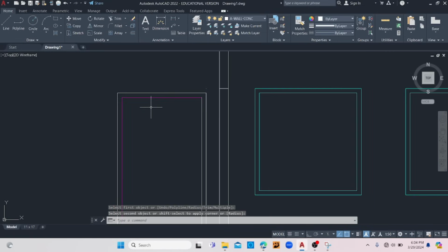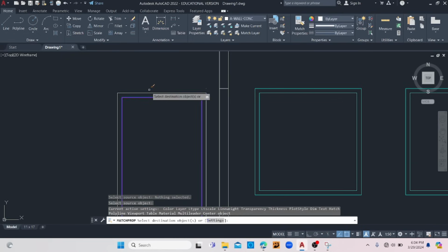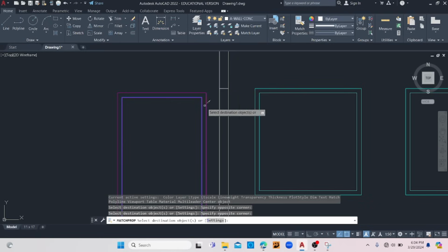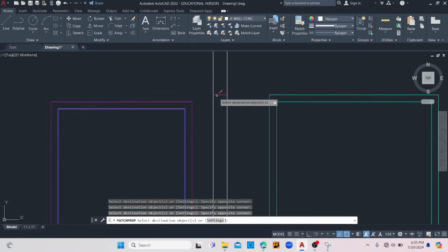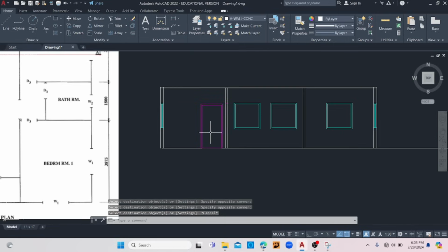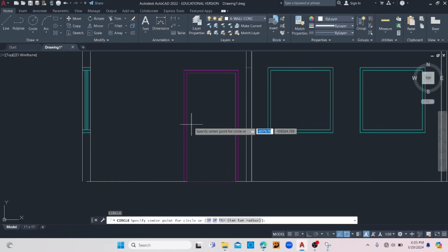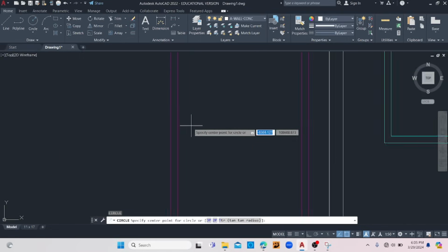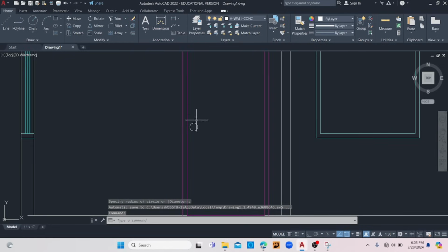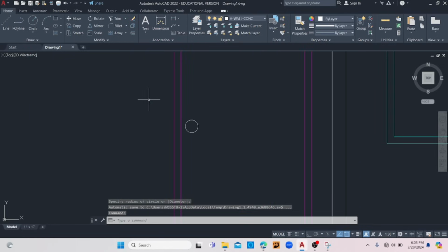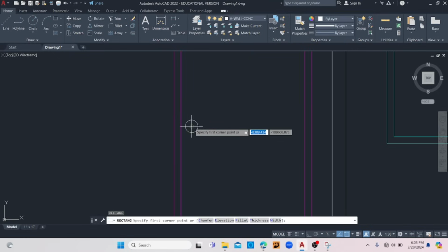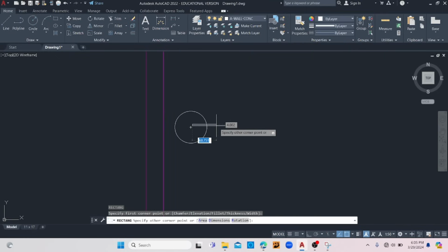Let's just place everything on the door layer. Let me do the same for the passage here earlier as well. Alright, and just add a little door, assuming that it swings on this side, a little door knob. I don't need anything more than that. Maybe I could do a little rectangle for the handle if we're using that type of handle.